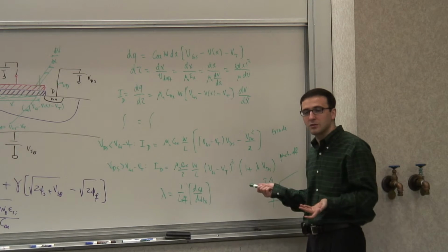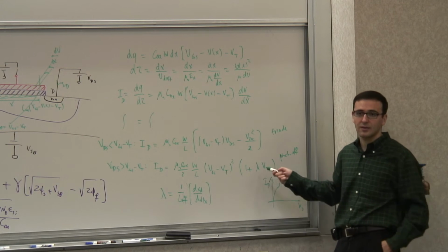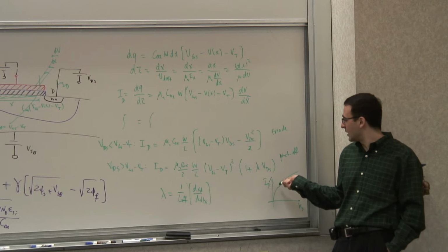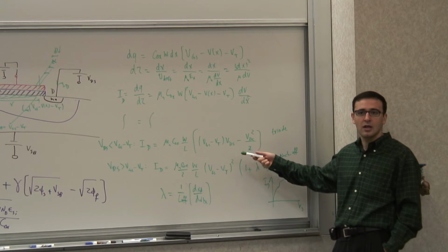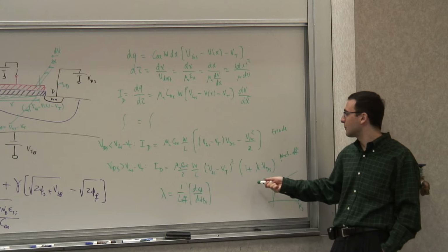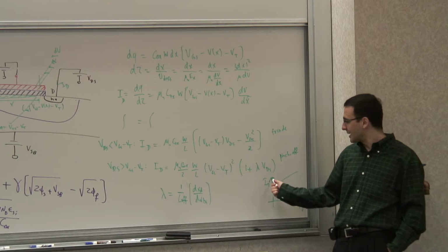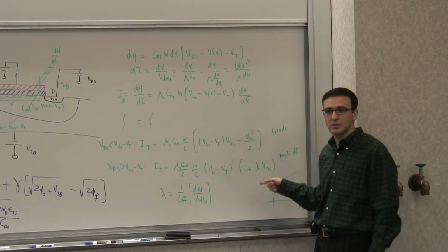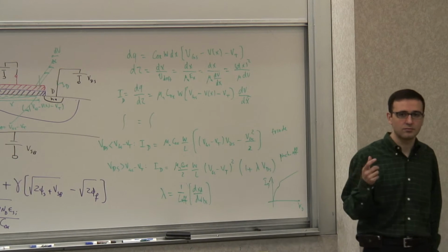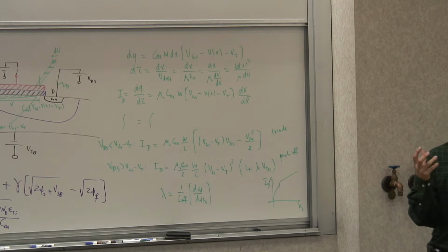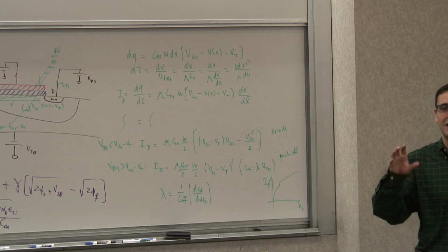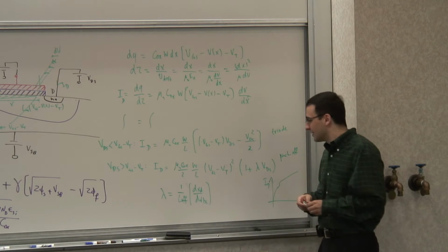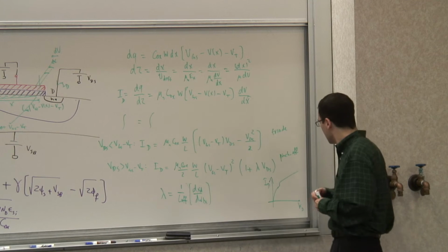So there are several different ways to deal with that. One is to realize that it is there. I've added the correction term here, and as long as I'm not in this region, live with it, and use that equation in my calculation, whenever I'm in triode, and use this equation for pinch-off, knowing that there's this kind of error. The other way is, but that would be a killer if you try to incorporate that into a simulator. Computer simulators are extremely sensitive to discontinuity, not only in value, but also in the derivatives. So if you have discontinuity like this, the simulator can go nuts. Right? So this is what can happen.